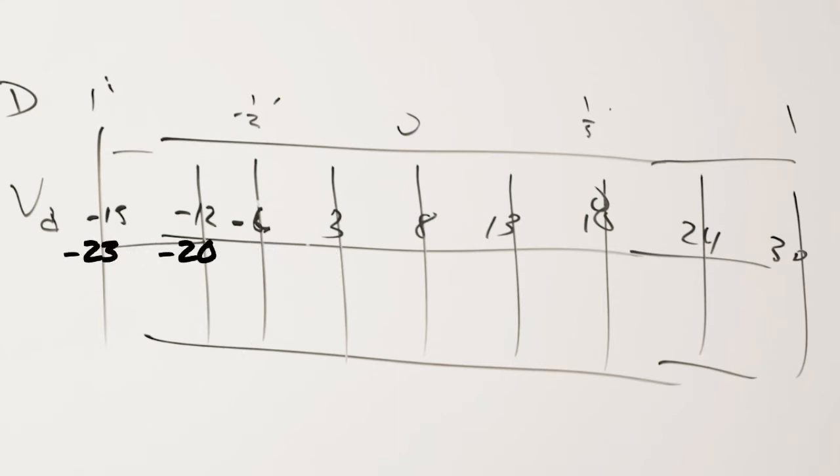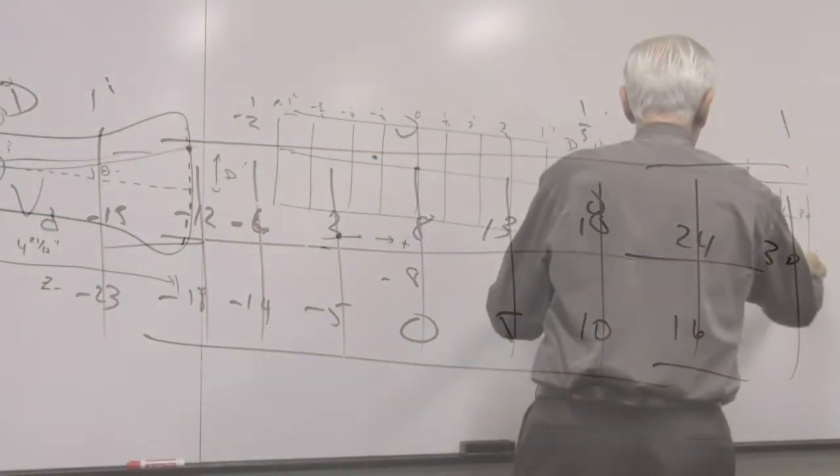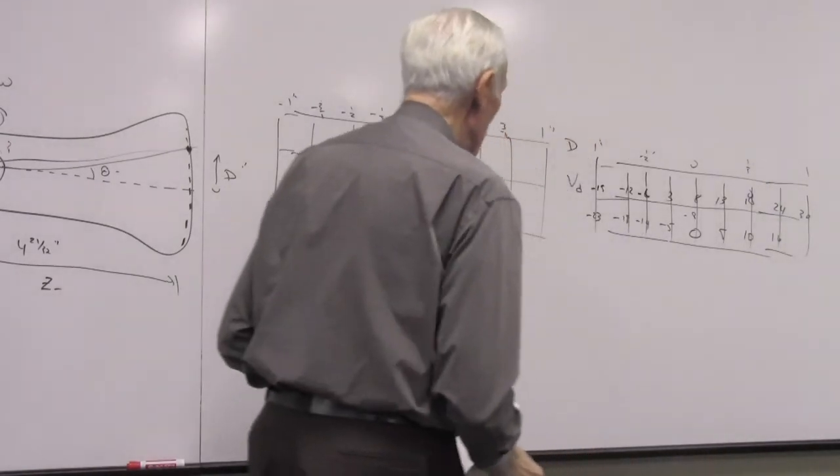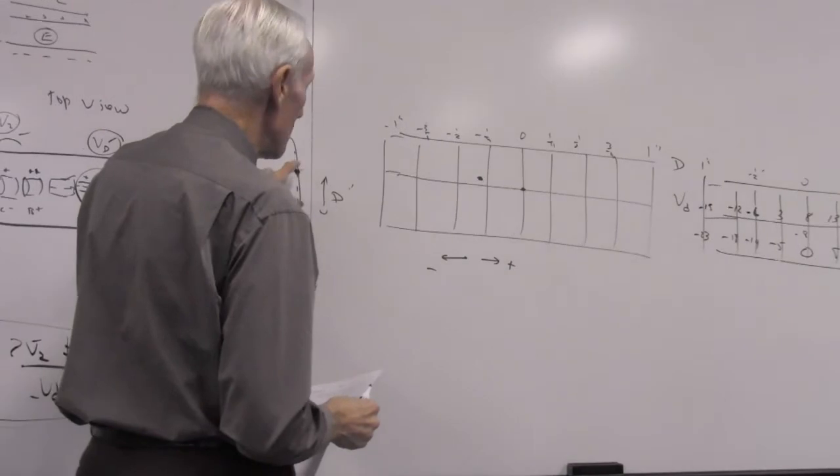So when you do this adjusting, you should see that the numbers on each side are pretty much the same, except for the plus or minus sign. And I'm just making these up, so I've not made them up very nicely. So what you need to do then is to average these numbers, forget about the sign, and that gives you the deflecting voltage to move it to 1/4, 1/2, 3/4, and 1 inch.